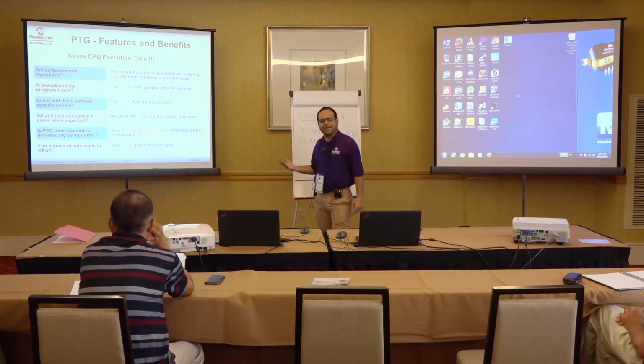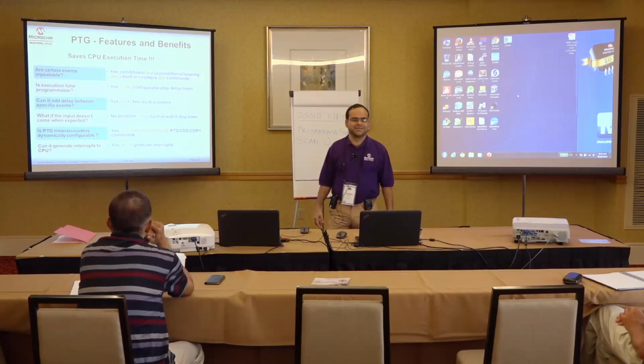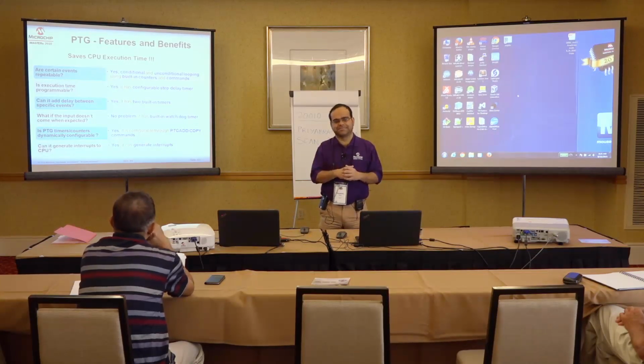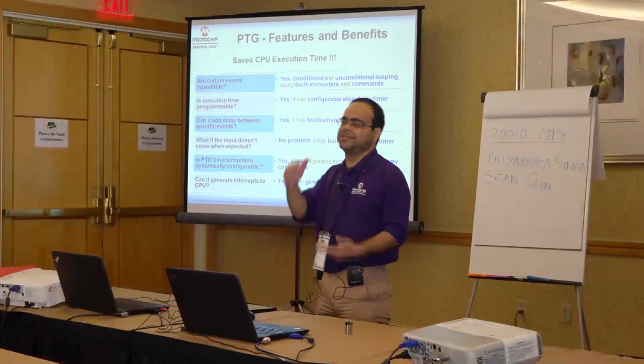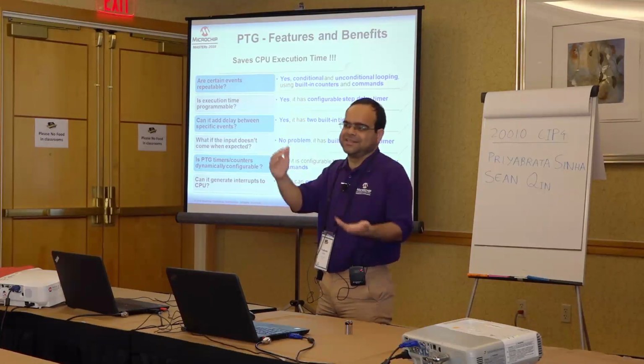These step commands are basically a set of control registers which you set up in advance, and then those get executed by the PTG module. In most of our devices that have PTG, there are up to 32 step commands. Some smaller memory devices might have up to 16 or 24.